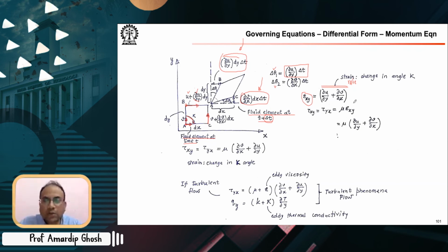Now from the basic stress strain, the way we say is you have the strain rate in this particular xy plane. In a Newtonian sense, this strain rate would be linearly related to the stress causing it. This is observed in most fluids, so that class of fluid is known as the Newtonian fluid.